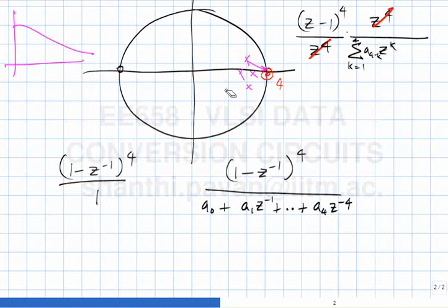If, instead of choosing the poles close to the origin, you went and chose the poles close to pi, then it's a double whammy, right? What would have been 16 will now become 60. And that's very easily possible if you mistake the order of a0 to a4, and if you make a4 equal to a0 and just transpose the matrix, you will get something where the outer band gain goes to a very, very large value. Yes, very good.